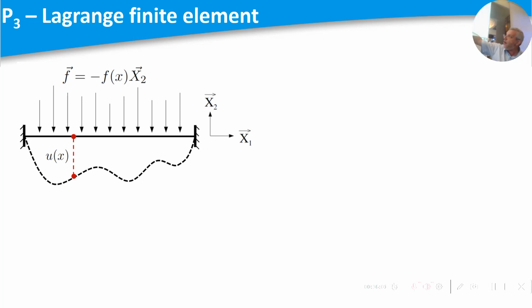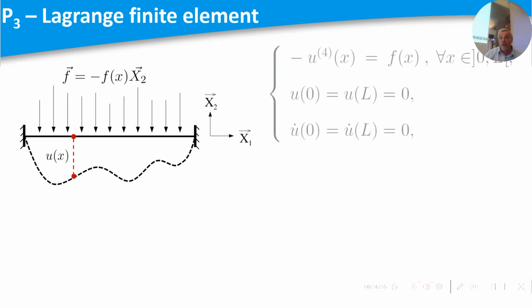Here you have a beam, which can describe a bridge, for example, and you have an external density of forces F(x), which models, for example, people, cars, wind, very complex external actions on the structure. And as a result, you have a displacement for any x between 0 and L, if L is the length of the bridge or the beam. And U(x) is the solution, with simple considerations of solid mechanics, to these differential equations.